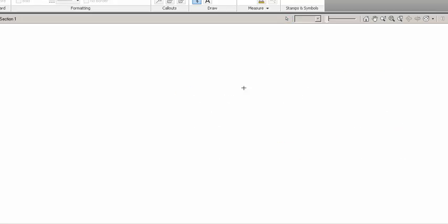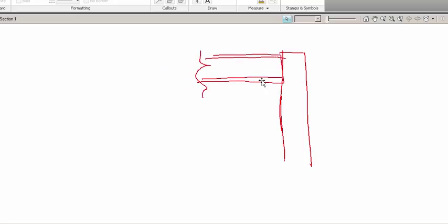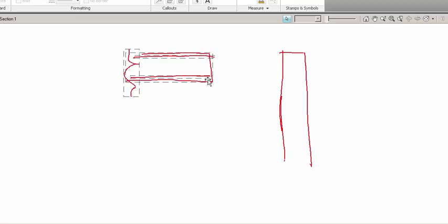For example, as I mentioned previously, when we tie beams and columns together. If we have a column here and we have a beam here, and this is just called a W-beam, we're seeing it from the side, and I want to connect this W-beam to this column. Well, you could try to hold it there in place and weld it, which doesn't work out too well. Or you could drill a couple holes in it right about here. You could go get a steel plate of a certain size and drill a couple holes in it.